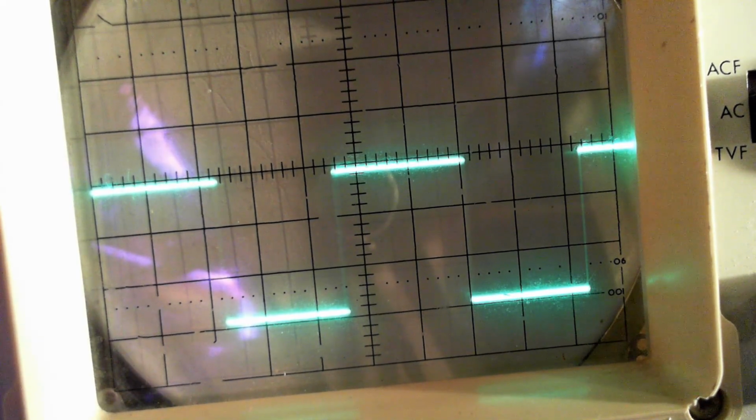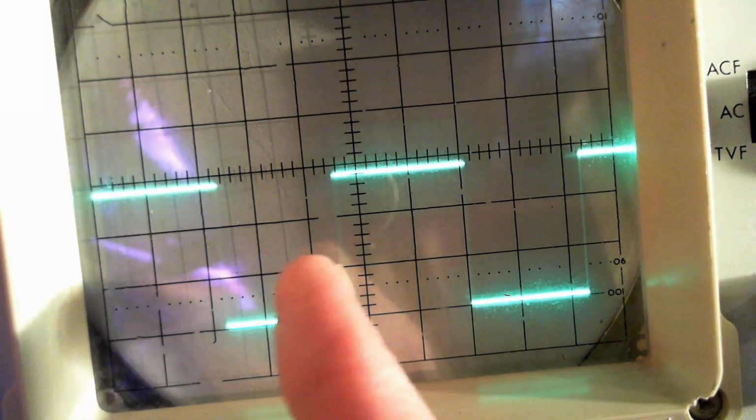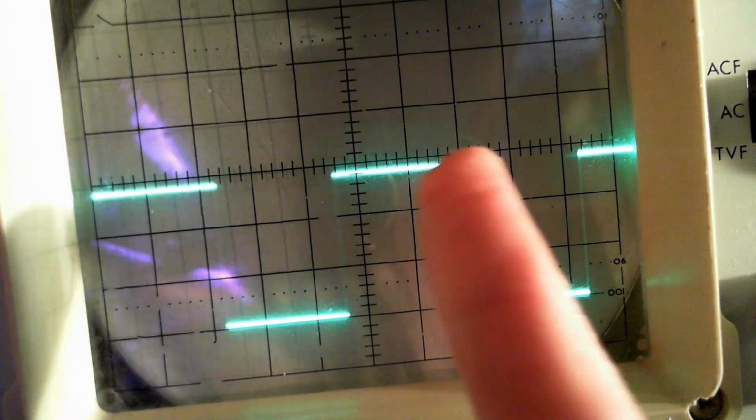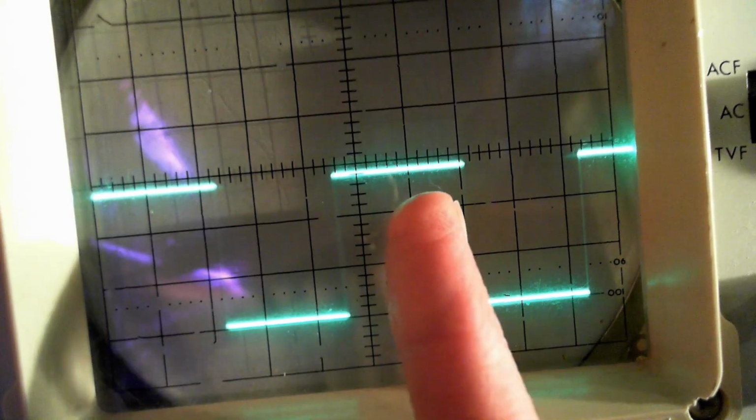Again, there's a parallax error in the camera, a slight one. So here, this should be exactly 3, 1, 2, 3, and it's slightly low. Looks like it just moved a bit. Slightly low. So that means the vertical amplifier needs to be increased. Vertical amplification needs to be increased a touch.